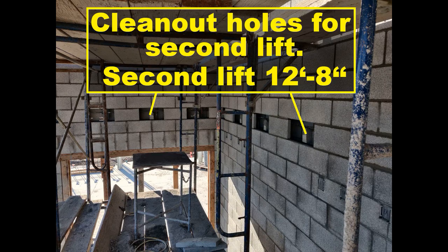If the masonry is cured at least 4 hours, grout slump is maintained between 10 to 11 inches, and no intermediate reinforced bond beams are placed between the top and bottom of the pour height, place conventional grout in lifts not exceeding 12 feet 8 inches. For the same curing and slump conditions but with intermediate bond beams, limit conventional grout lift to the bottom of the lowest bond beam that is more than 5 feet 4 inches above the bottom of the lift, but do not exceed 12 feet 8 inches.